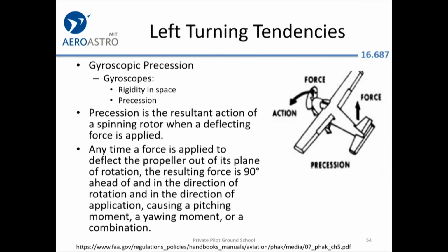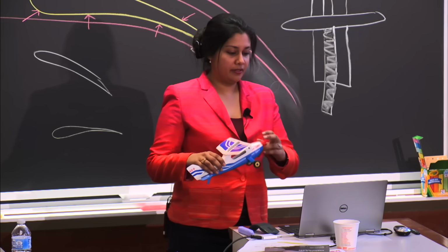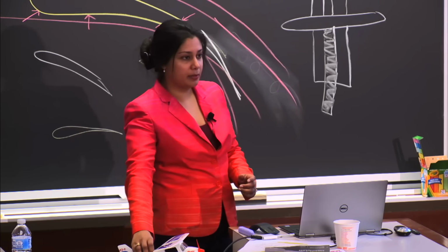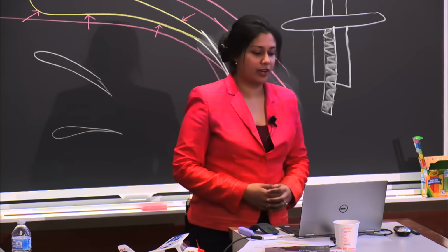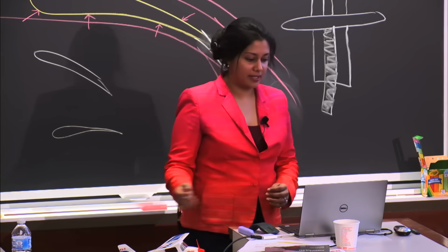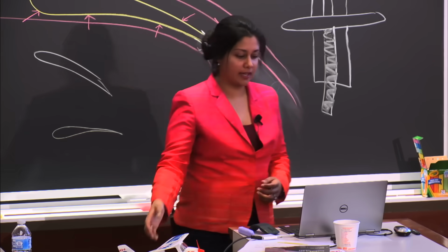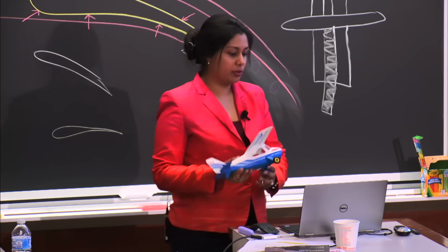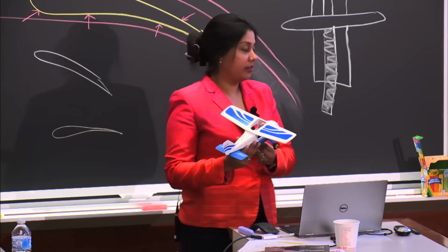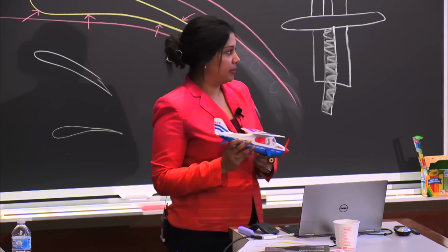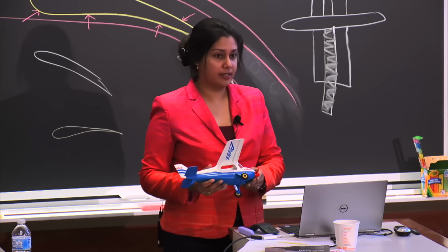Because of that, you have the propeller spinning, and that causes this gyroscopic precession, and that causes 90 degrees out of sync a force, which causes a yawing movement, a pitching and a yawing in this case.